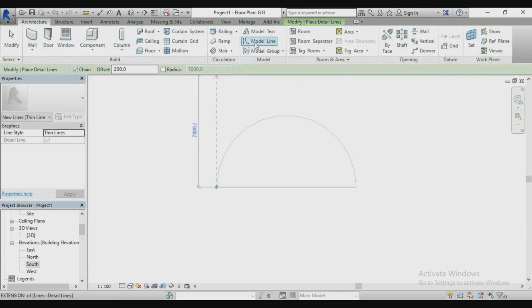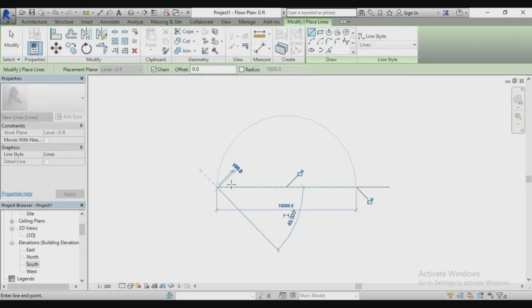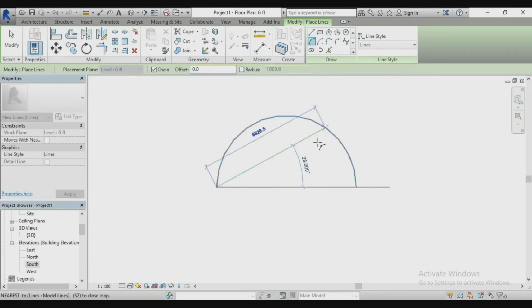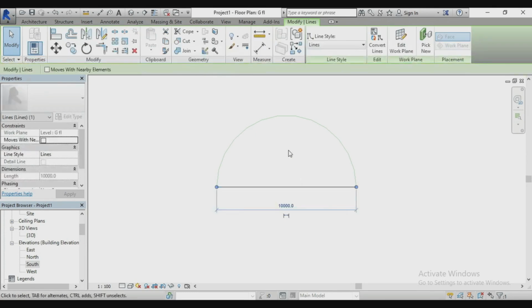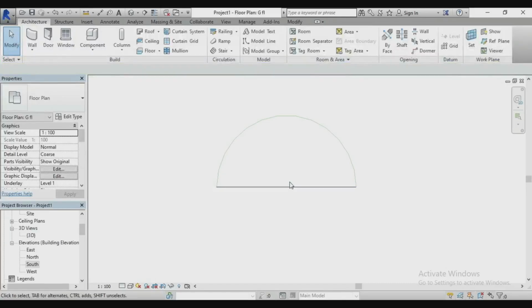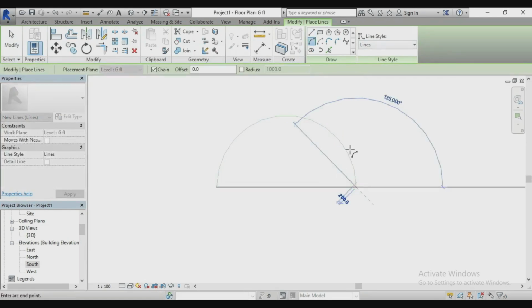Yeah, I picked a detailed line, so ensure you pick a modeling line, LI, enter, and you draw. I picked a straight line, so ensure you pick the arc, modeling line arc, LI, then pick start, end and radius arc. Draw from your left.